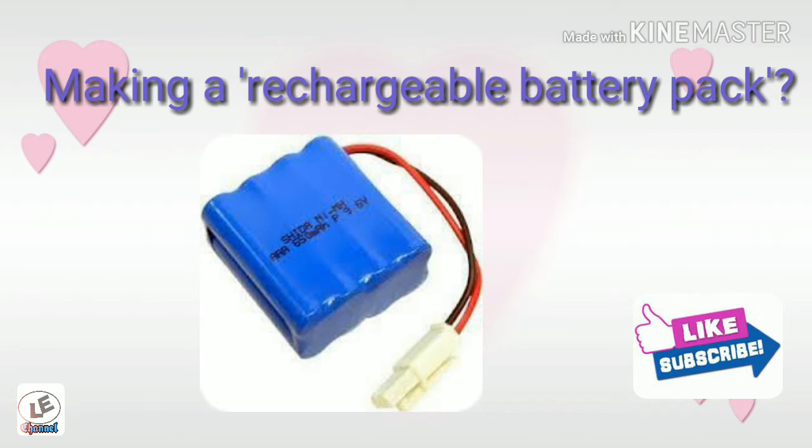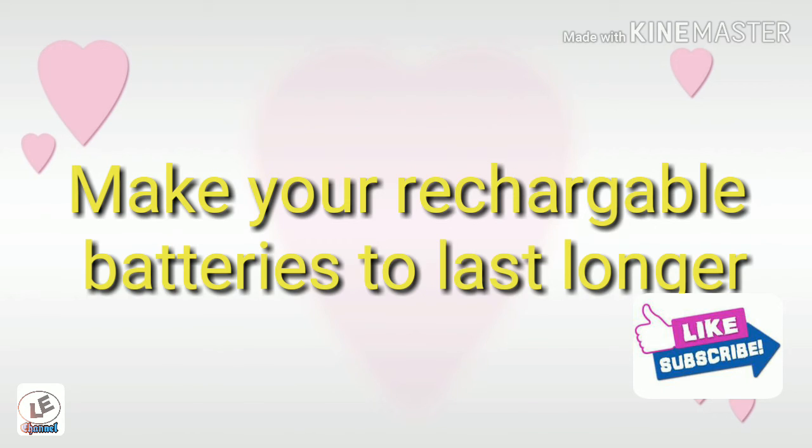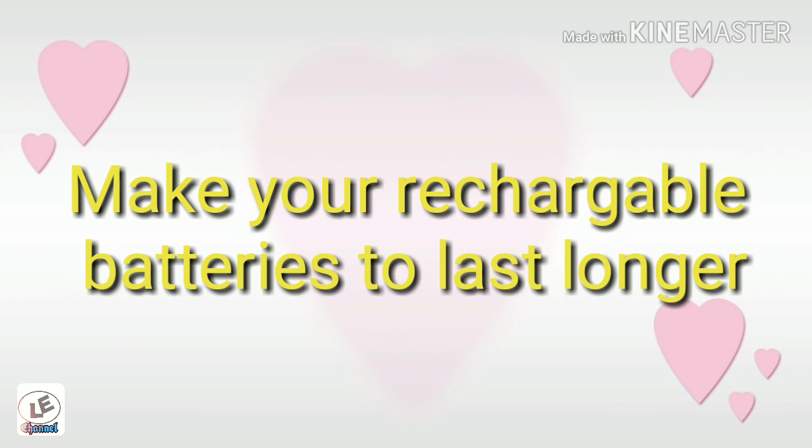And if you want to make a rechargeable battery pack, then you can use a battery holder and stick with nickel metal hydride batteries, and you can charge them with a charger. If you want your rechargeable batteries to last a longer time, then use a high quality charger, and let the charger have sensors to maintain proper charging, or even sometimes trickle charging. If you use a cheap charger, then your battery may not last long.